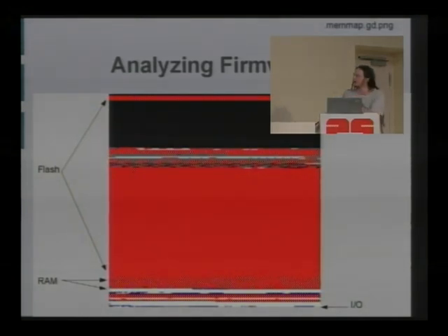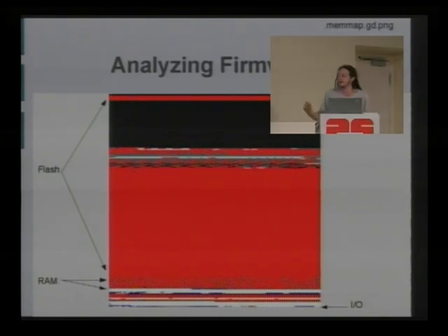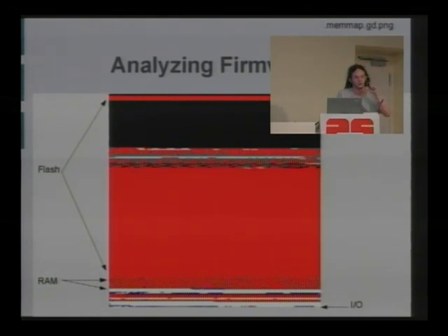So in 2 days, I wrote this analysis system in Perl, and this whole graph is done by a couple of SQL queries. Everything in red is a number other than 0 or -1. Everything in white is a 0. You'll note that RAM is zeroed out toward the bottom because that's what RAM does when it's reset. Flash memory resets to 1s. So you reset the entire sector to 1s, and then to write a byte to it, you move individual bits from a 1 to a 0. So all of the flash memory at the top that hasn't been initialized is in black.